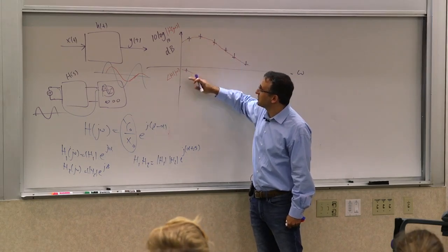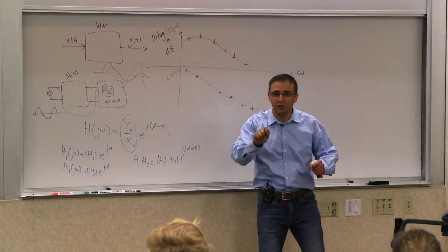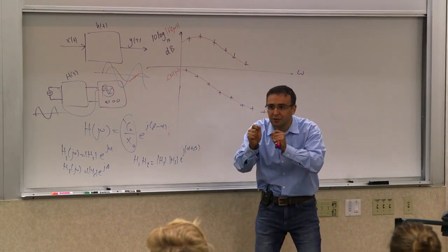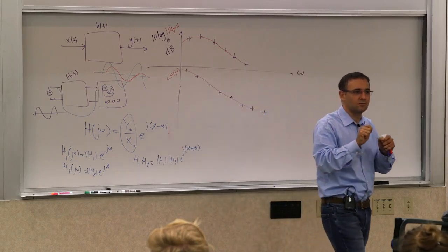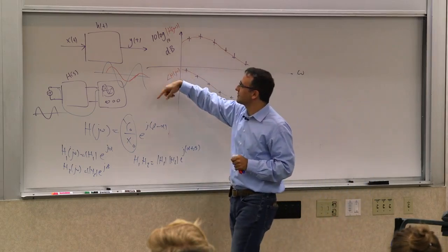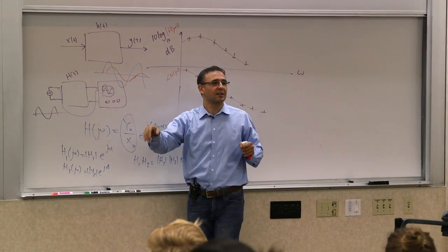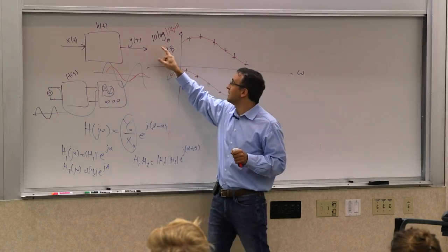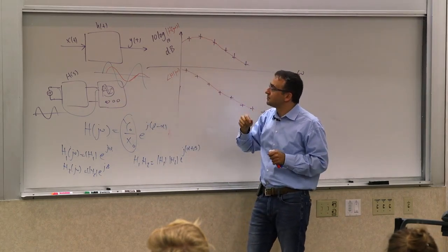So once you express this in decibel, the beauty of this is that you can measure these in the lab with pretty benign systems. You don't have to look at the transient response very quickly before it goes away. If you blink, it's not gone. It's the sine wave, it's there constantly, and then you put an input, and you see the output, and you have time to measure it. You measure this phase difference and amplitude, and then you plot the 10 log of that.